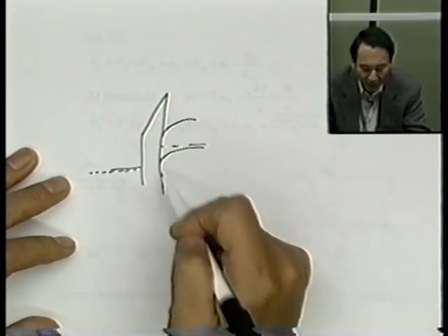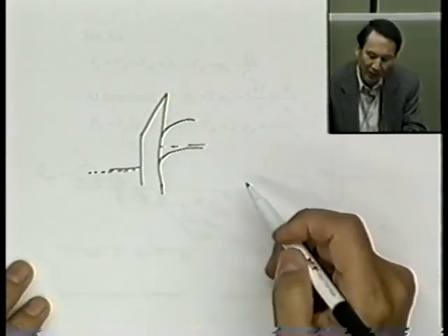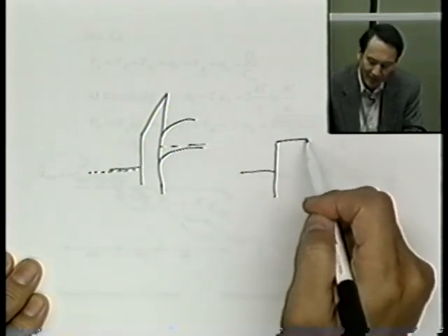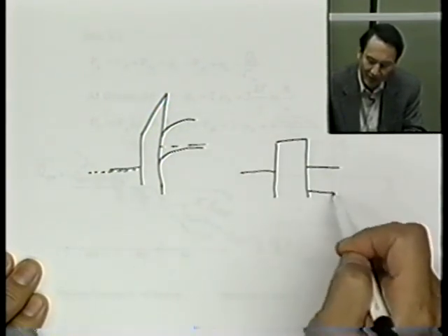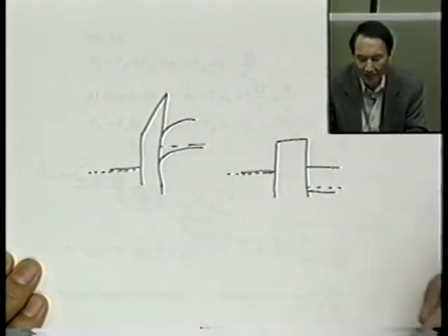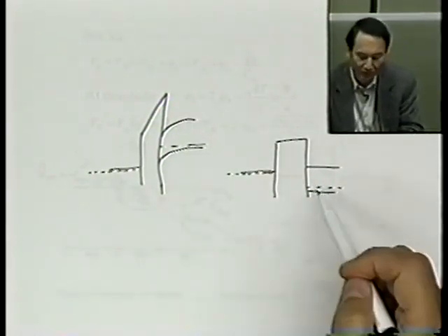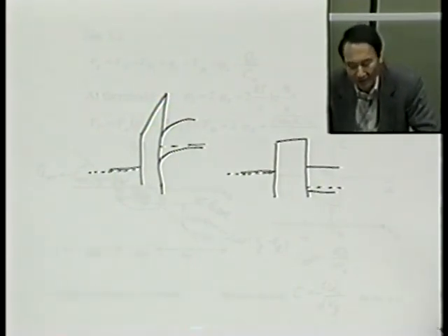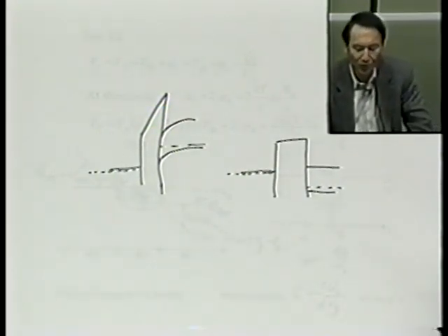What about the Fermi level in the oxide? Or to take an even simpler case, the so-called flat band case, there's a Fermi level in the substrate, a Fermi level in the gate, and a voltage difference. What about the Fermi level in the oxide? Shouldn't we pay some attention to it?